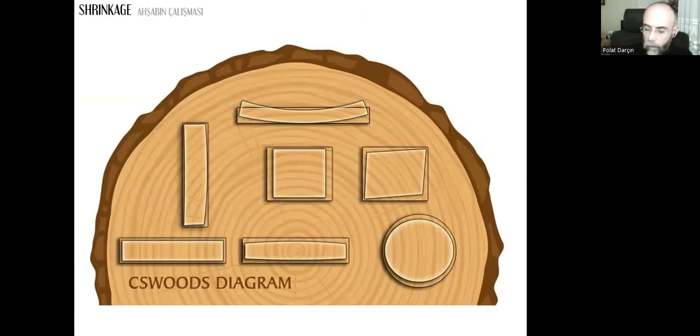It will be very useful because single solid timber pieces, they shrink. They will swell if they are placed in a humid environment. All the humidity, water in gas form in the air will be sucked into the voids of these timber pieces and they will deform. You remember that there are different types of deformations based on the location of these timber pieces on the tree trunk, based on the position of the pit.